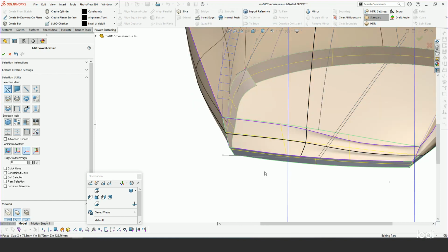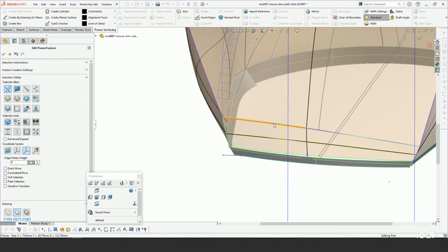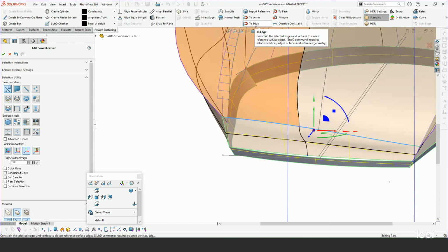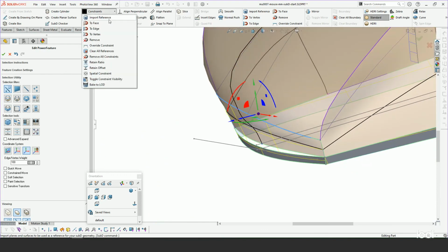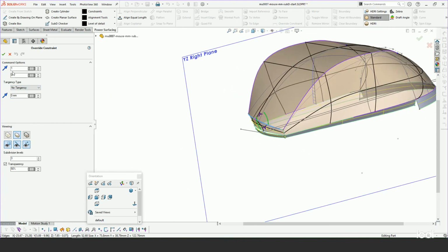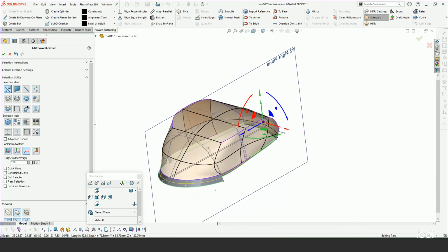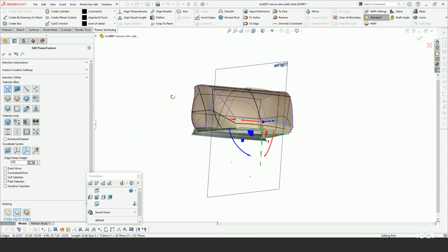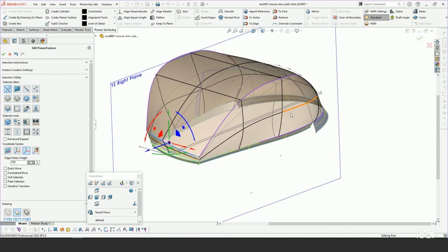Yeah, and then let's just make sure that we've done that for all of them here. So I'll pick all these faces. And now let's try it the other way. Let's just say we want these edges to be constrained to the edge of the model. And I think that's probably the better way to go. You can see that it automatically made tangency. So again, you go to Constraints Override and you turn off tangency. So there we have everything that we need to be constrained, and we can move on in our model to start to reshape it the way we want.